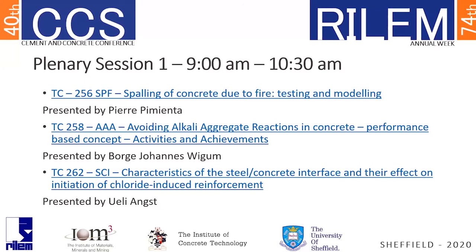Well, the point why we listed polishing is because this is sometimes, or actually quite frequently, used when preparing laboratory specimens, because people wanted to ensure that you have reproducible conditions. The best way to do that is to polish the surface, because then you're sure what you have at the steel surface. But that is, of course, not very representative for practical conditions. And it has consistently been found that polishing the steel surface increases considerably the resistance against chloride-induced corrosion. So laboratory studies using that are for sure not applicable to practical conditions.